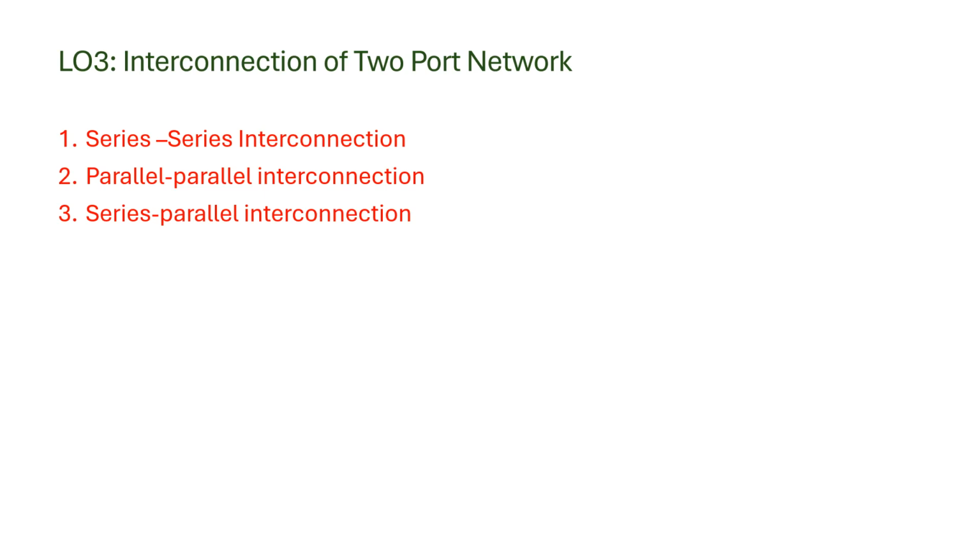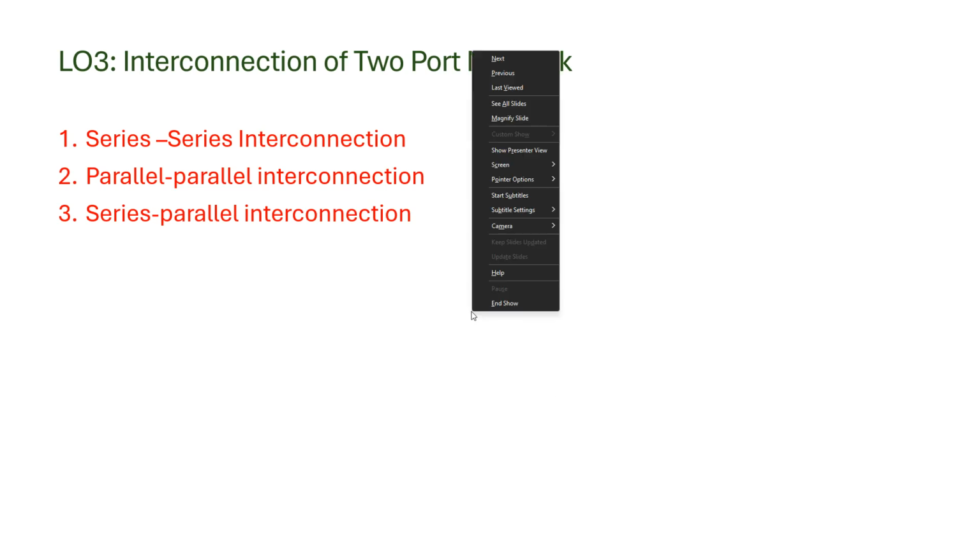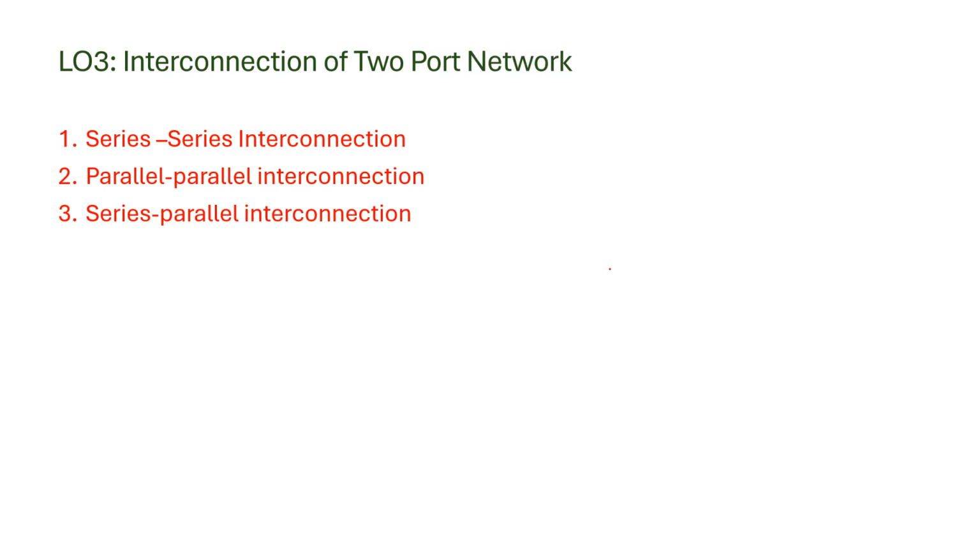In this interconnection of two-port network, we shall deal with series-series interconnection, then parallel-parallel interconnection, then series-parallel interconnection. This knowledge of interconnection of two-port network is required to analyze the simultaneous faults.